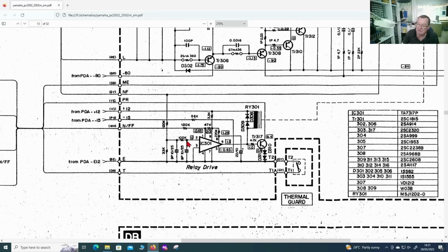So the voltage on here can be positive or negative. This chip detects there is a voltage regardless of the polarity, which an op amp won't itself quite do, and it switches the relay accordingly. Another thing, when the amplifier is running, on here is the actual AC waveform, the audio waveform, going positive and negative all the time. It doesn't keep switching the relay on and off. It knows the difference between an AC signal and a DC offset.